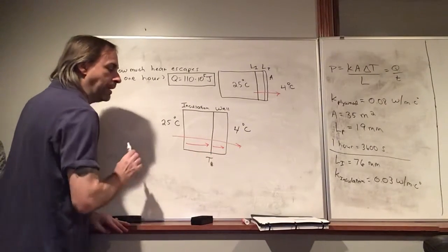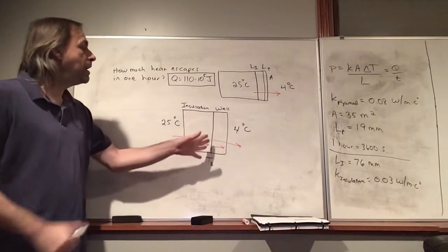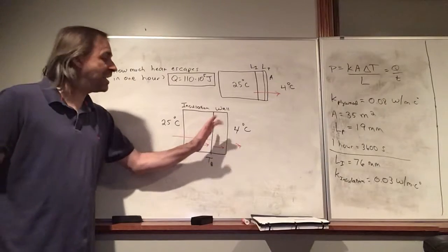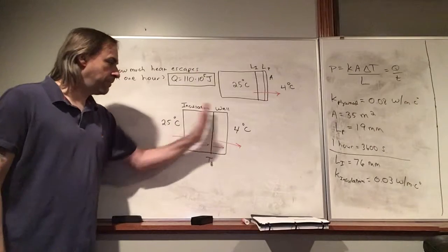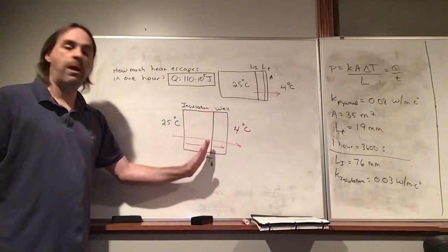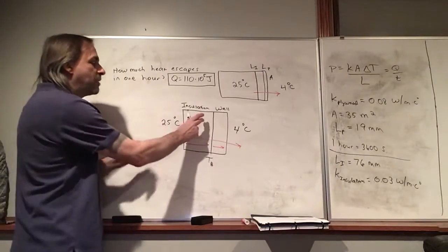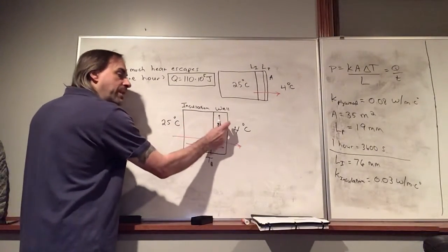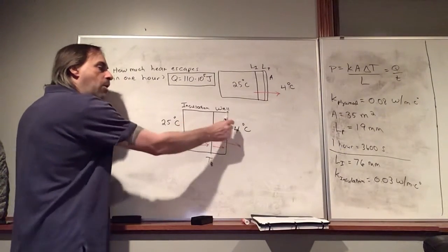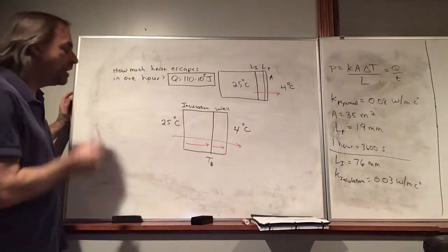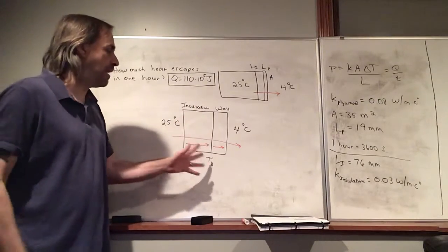We don't know what that is right now. But let's say that was 10 degrees. Again, if heat was flowing through the insulation faster than it's flowing through the wall, there'd be a net heat building up on this boundary, which would heat it up. And so if we raise this temperature, that's lowering the delta T here and increasing it here. If we change this from, say, 10 to 15, this delta T gets smaller, this delta T gets bigger, and so that would lower the temperature of the boundary.